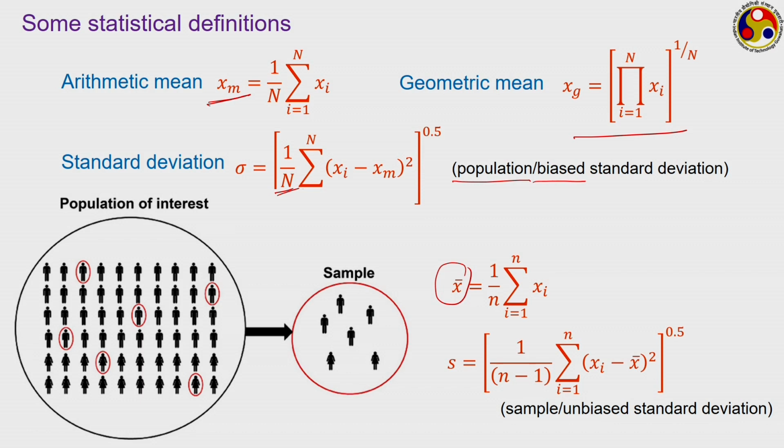Let me take an example. Suppose we are trying to measure the pressure of steam going out from a boiler towards a turbine. We can monitor the pressure value using any suitable pressure measuring instrument. Pressure can be measured at every time interval. Depending upon the resolution and time stability of your instrument, you can measure the pressure after every 1 second, 1 millisecond, or 1 microsecond, thereby providing an infinite set of data. But practically it may not be possible to handle so many measurements.